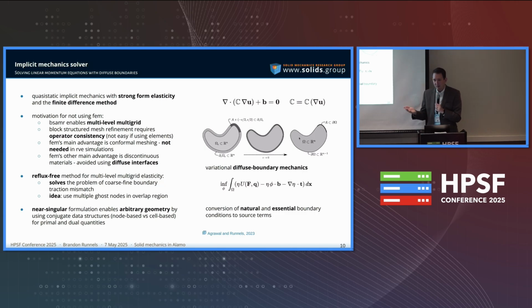And we said, well, we want to be able to solve these equations too using AMReX, but we really don't want to do finite elements. Finite elements doesn't make any sense at all on an AMReX grid. But an operator like this is also very difficult to do with something like MLMG. This is this elasticity tensor. It's a 3 by 3 by 3 by 3 tensor, which has 81 components. You usually reduce it down to like 2, but that's not something that MLMG was previously able to do. So that's one of the reasons why we really started working closely with the AMReX team, trying to work this in.